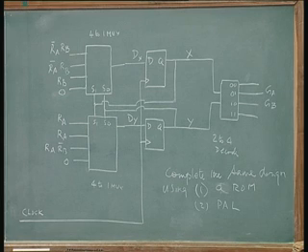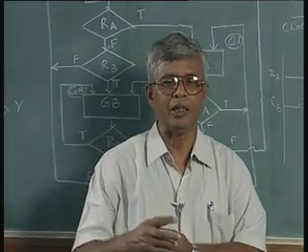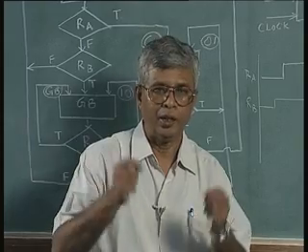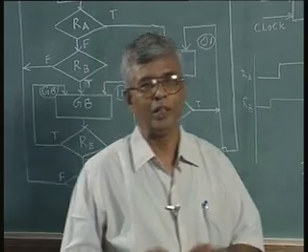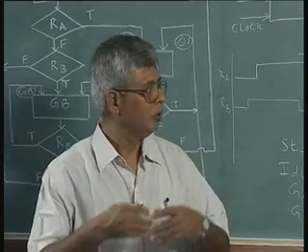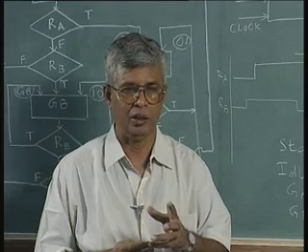So, to just summarize the approach of ASM based design, we have this partitioning technique where you have a top down approach. You look at the problem, identify how it can be partitioned into functional units which are readily available, so we do not have to design them, and choose them such that we have enough controls. If you want to clear a register, you should have a clear control. If you want to increment a register, you should have increment inputs. These are things you have to look at, and once you partition the problem, you get all the input and output signals required for the functional units.